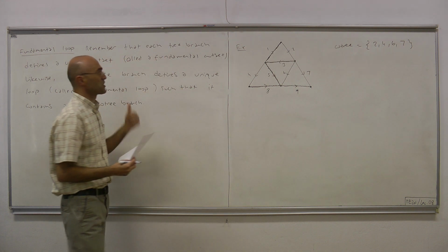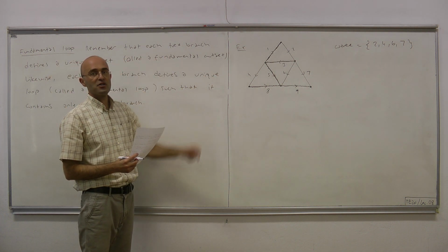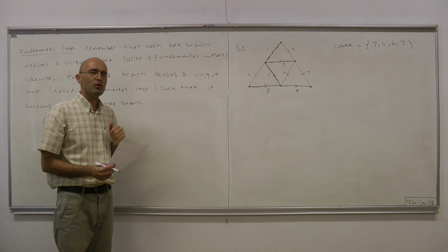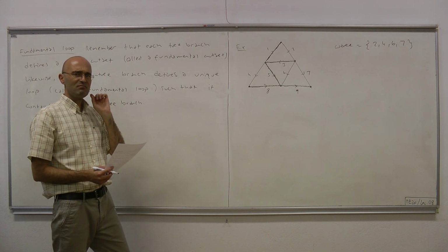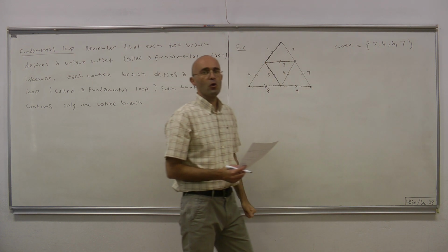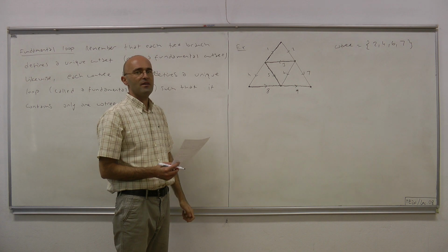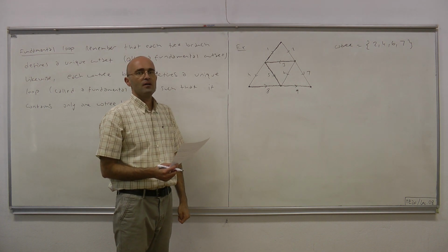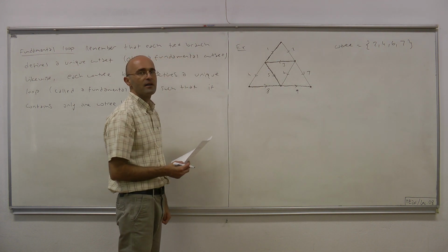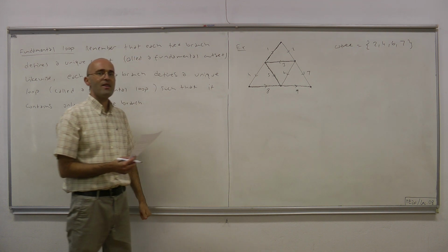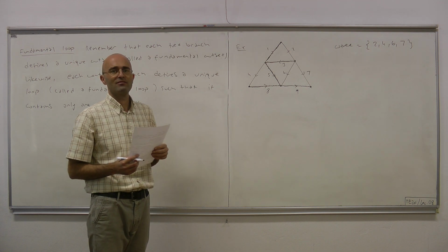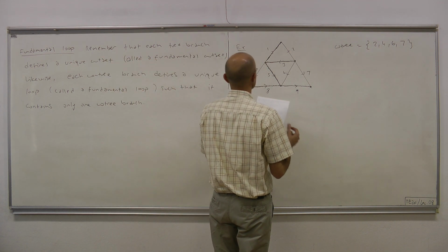Now here, it was claimed that each of those branches, 2, 4, 6, and 7, can be used to define a closed loop path in such a way that the loop contains only one cotree branch, and all the remaining branches in that loop are coming from the tree branches, namely branches 1, 3, 5, 8, and 9. Part of the claim is that the loop must always be unique for a given cotree branch. Okay, so let's see whether that's true, at least for this example.